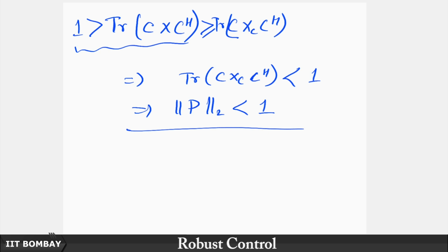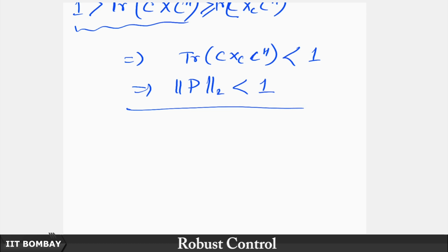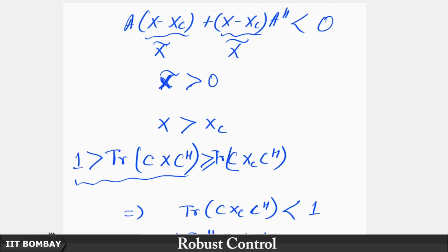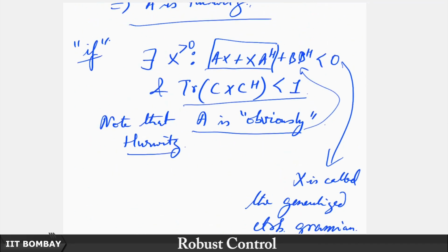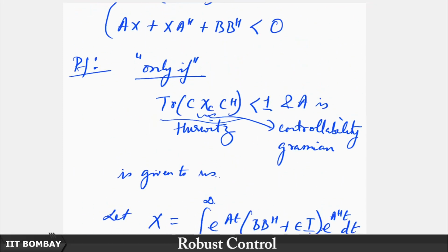Okay. So, when we meet for the next lecture, we will see how this formulation, already half the game is won, as they say, because we have been able to show you that this H2 optimization problem, or H2 optimal control problem, has an equivalent LMI formulation, which is an exact equivalence. So, if we can now show you a method to obtain a solution for this formulation, it is not really completely an LMI, it is not very obvious to see yet, but you already see a hint of an LMI in the sense that there is an inequality.